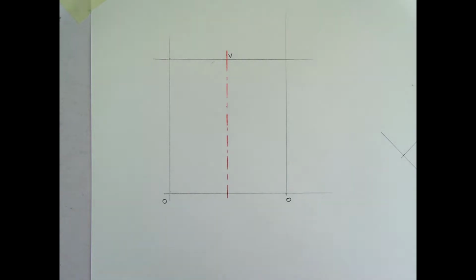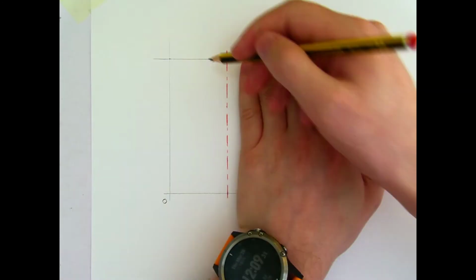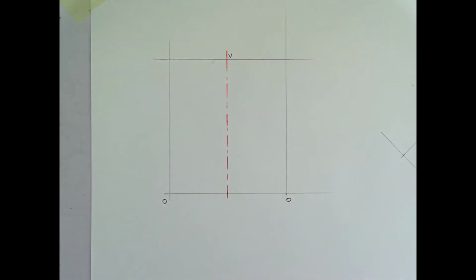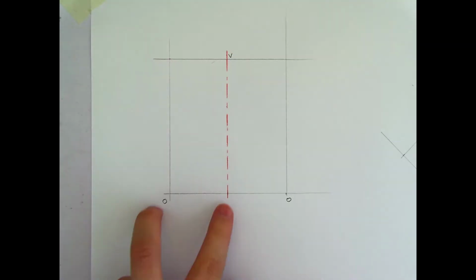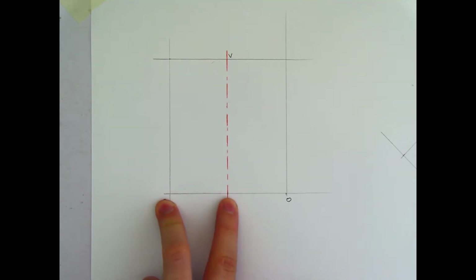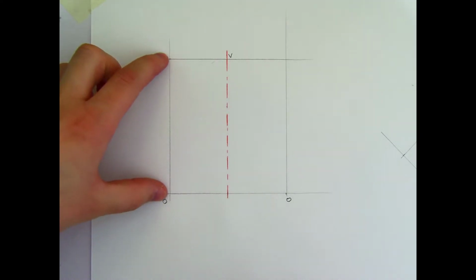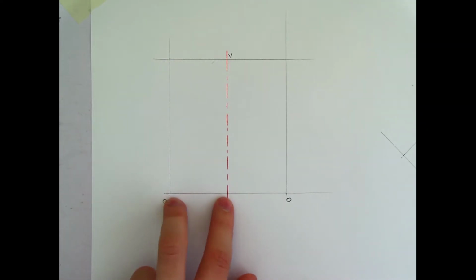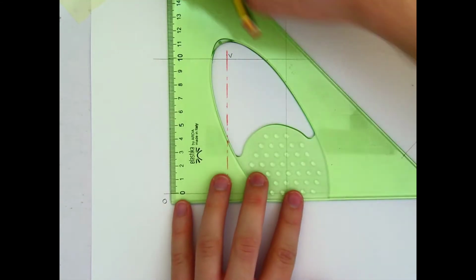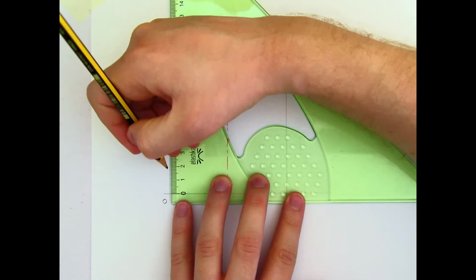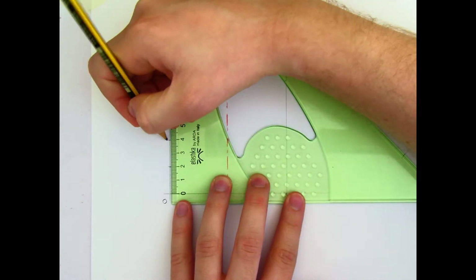So what I'm going to do is take each half of the rectangle separately. I'm going to take the left half first, and then I can worry about the right hand side afterwards. For my rectangle method, I need to divide the sides, this side and this side as far as the axis only, up into the same number of equal parts. If this is 100 tall, I can divide this up into 5 equal parts. If I do 5 equal parts here, each section is 20 millimeters,